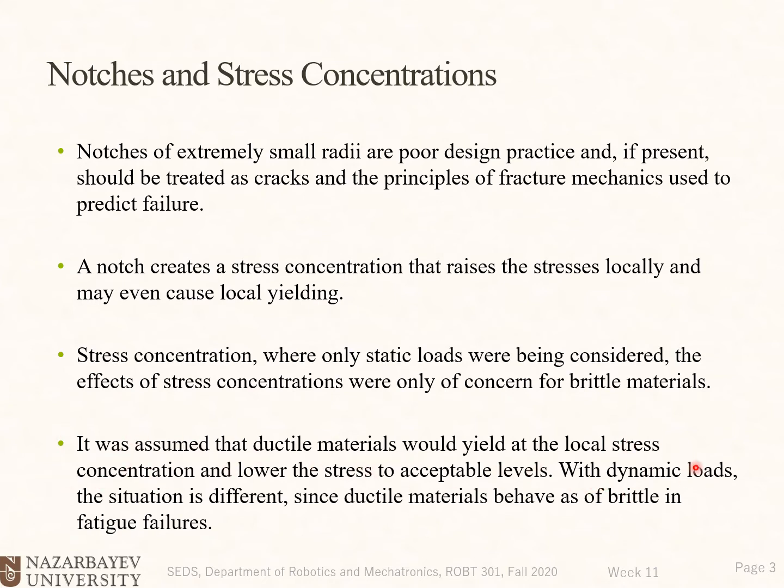With dynamic loads, the situation is different, since ductile materials behave as if brittle in fatigue failures. Okay, so now we see that for dynamic loads or fatigue loads, ductile materials behave the same as brittle materials. And for both of these cases, the stress concentration will be of importance.